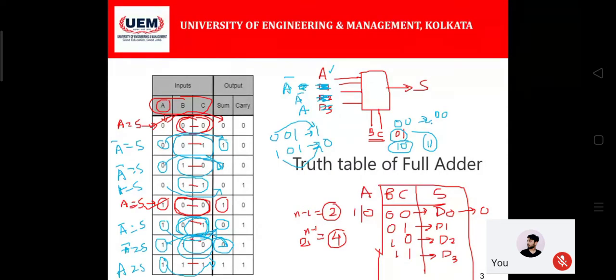So now, as you can see, our multiplexer has 6 inputs including the select lines and the input lines, but now it already follows all the possible combinations of the inputs with the proper sum output. This full multiplexer will now behave like a full adder sum part.